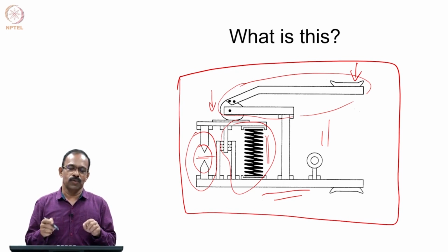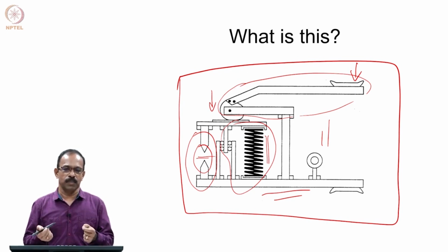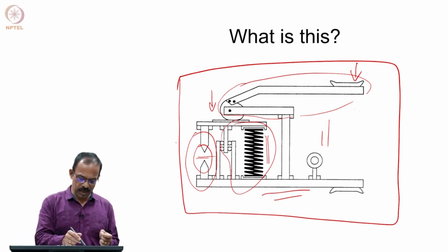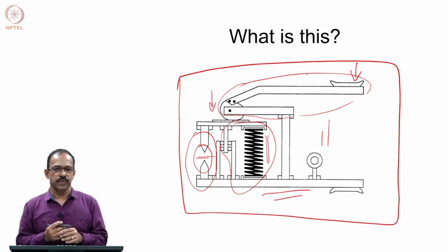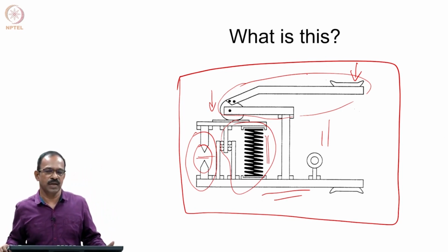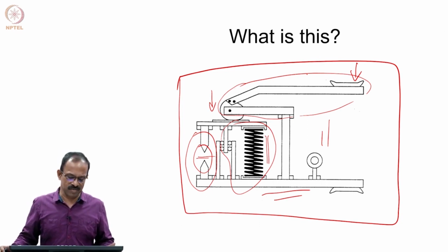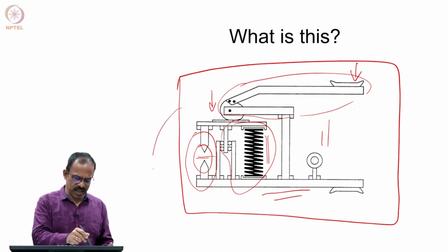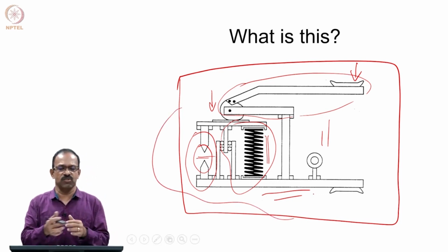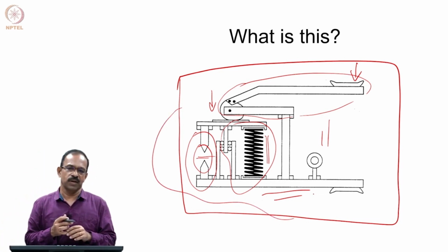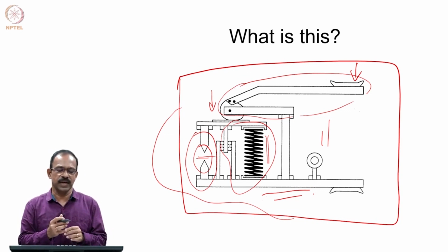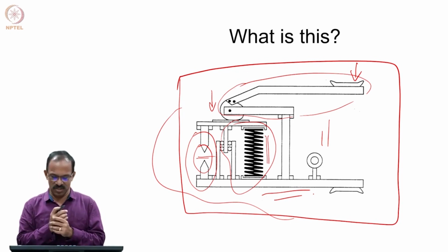So, if you look at a nail clipper as a modular structure, then you will be able to get these many modules, but most nail clippers are not designed in modular architecture. They are made in an integral architecture where you cannot really change each one of these, because the functions are shared between the physical chunks, and you will not be able to get a clear differentiation between the physical chunks which provide the functions.